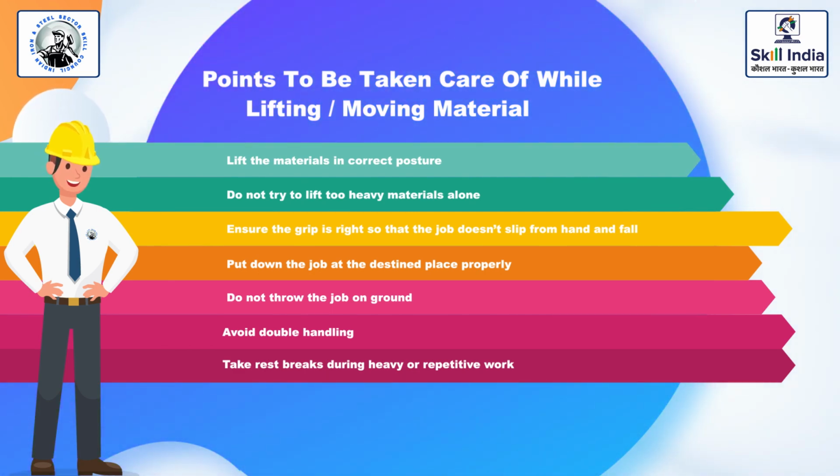You should also be attentive when you are assisting anyone during lifting or attaching the job to the overhead crane's sling or hook. If you are lifting or moving material, you must lift the material in the correct posture as shown in the image and also have a firm grip. If the material is too heavy, take someone's help. Place the material at its destination properly. Do not throw it on the ground. In case the job is repetitive or heavy, take breaks.